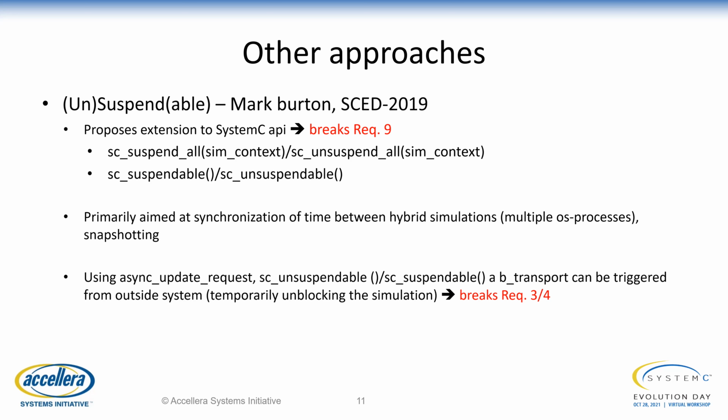Basically, that would break requirement number 9 for me, because I was not allowed to use a non-official SystemC version. But still, there were some pretty interesting ideas there. He had the suspend all, unsuspend all, suspendable, unsuspendable concepts. But his aim was primarily the synchronization of time between hybrid simulations and multiple OS processes.